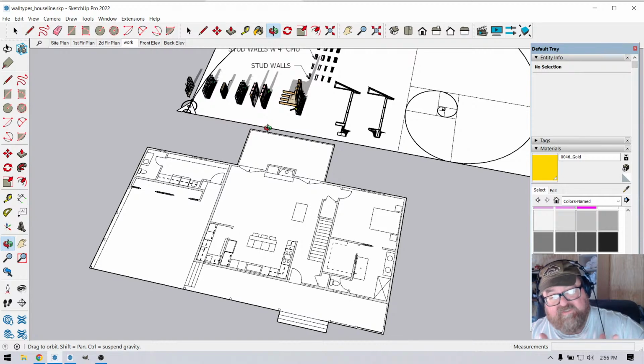So one of the first things they will ask you for, once you ask them for that first draw, which is a foundation draw, is, where is your foundation survey? And you'll say, oh yeah, I got to get one of those. So you'll run out, you'll get your surveyor, but guess what? You don't actually run out and get a surveyor at that point. A contractor gets a surveyor at the beginning of the project.